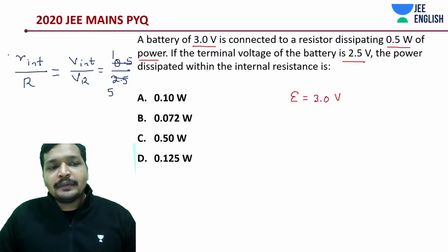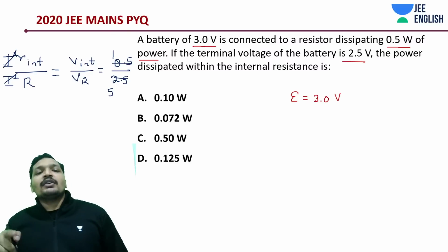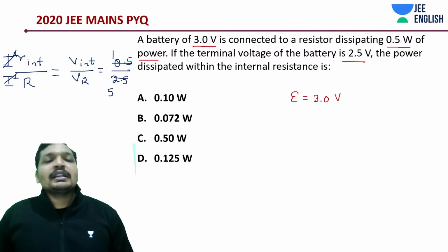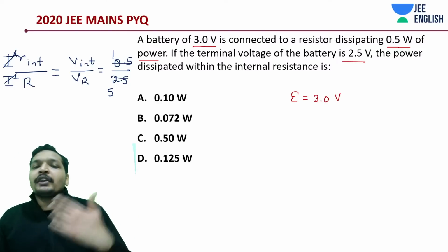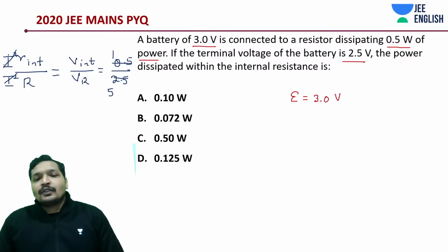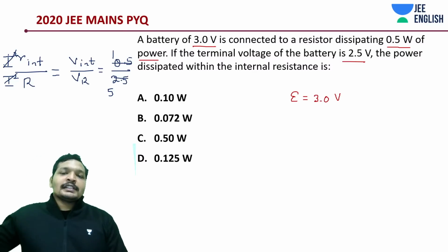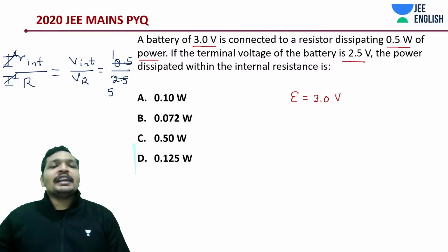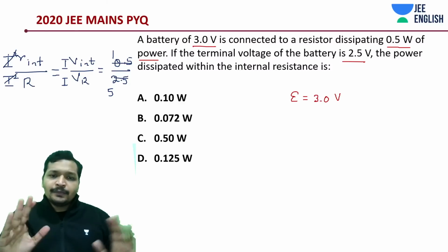I square R. How are we getting this? This is the power ratio I'm talking about. Okay, it's not the resistance ratio. It's I square R. I'm not basically writing down the I square R. I did not write it down intentionally until the end so that you should be understanding it. It's 1/5 of it, so it should be 0.1 watts. That's it. 0.5 volts is lost. Who took that 0.5 volts? It's V into I, which is also another way of thinking about it. You can think about it as I into V, because the same current is going to flow.